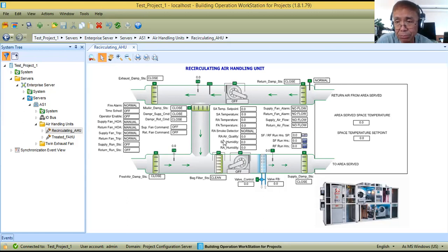Now, this start-stop point will basically have voltage in that BMS point, maybe 24 volts. It depends on the control transformer or the control voltage of the motor control. Basically, the motor control voltage is around 24 volts. Okay, so it's very seldom you will find 220.